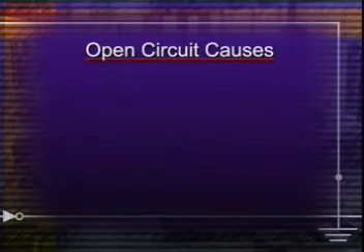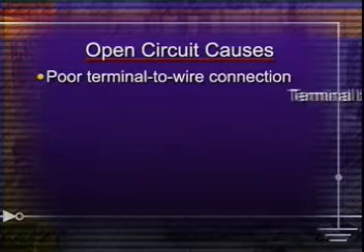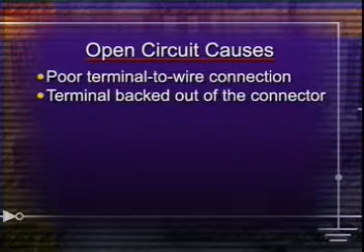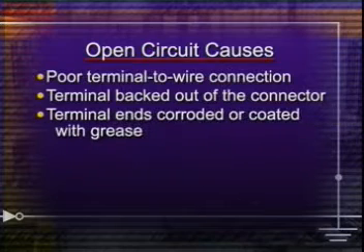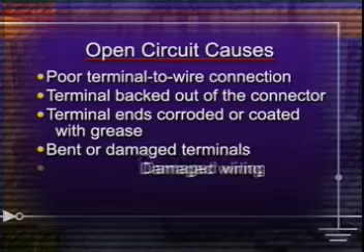There are many possible causes for open circuits, including poor terminal-to-wire connection, terminal backed out of the connector, terminal ends corroded or coated with grease, bent or damaged terminals, damaged wiring.